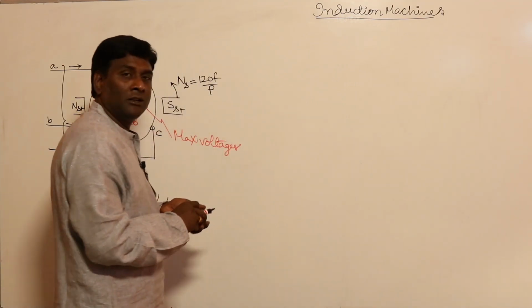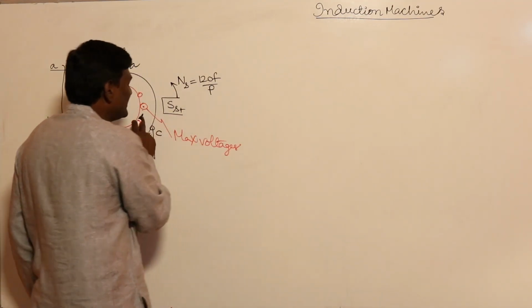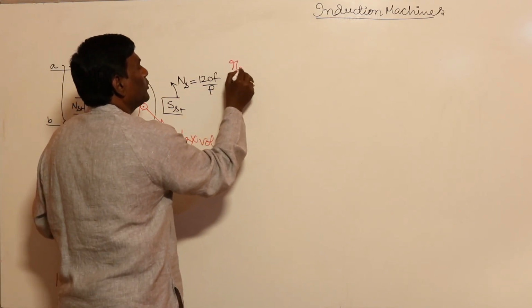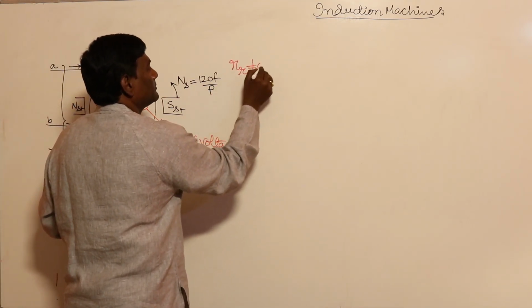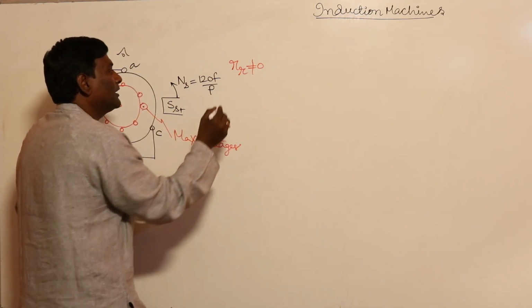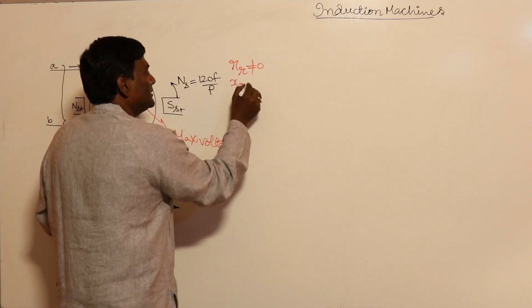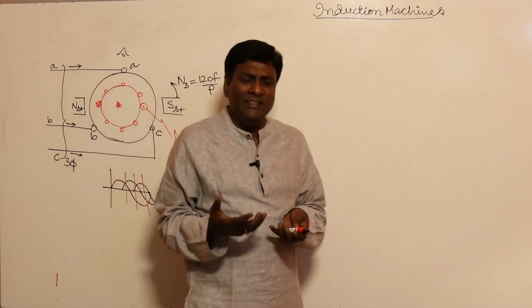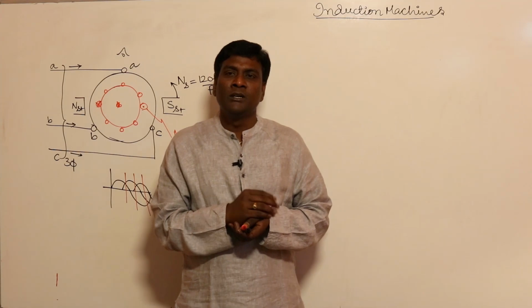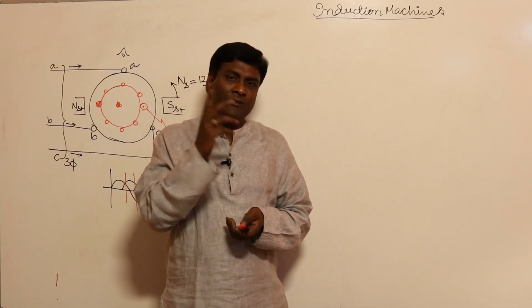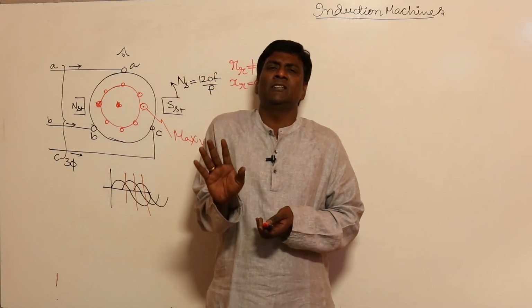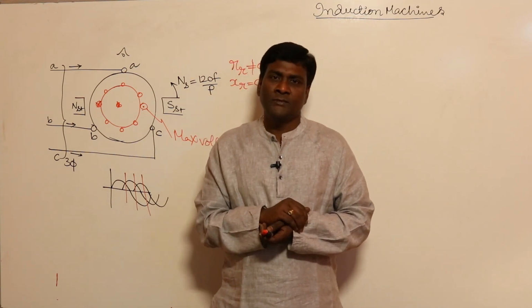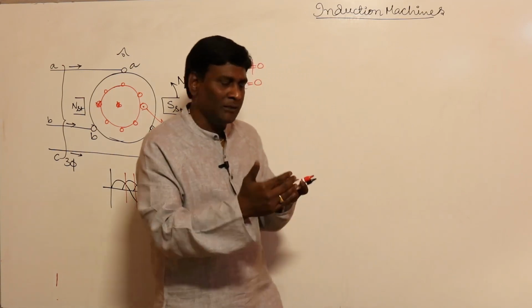For example, as of now, let me consider the rotor. The rotor has non-zero rotor resistance, and for example, rotor reactance is 0. Reactance comes because of leakage. More about leakage reactances I will discuss in the detailed course. Somehow leakage will be there, and that leakage will be modeled with the inductance. Just keep that point in mind because this is a simplified course.